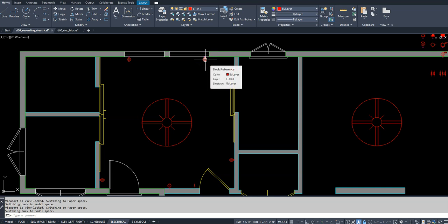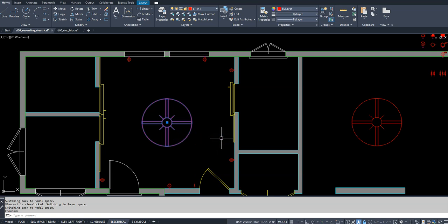So this is an all hot outlet. Again, if you wanted to do the half hot, half not, meaning it's going to be controlled by a switch, then that's what you would do. So if we said that we're going to control this fan with the switch, we could do that, or we could have a remote control for the fan itself and have it hardwired into the ceiling. So the fan is going to be always hardwired into the ceiling, no matter if it's on a switch or on a remote control, so that it can be powered through the ceiling.